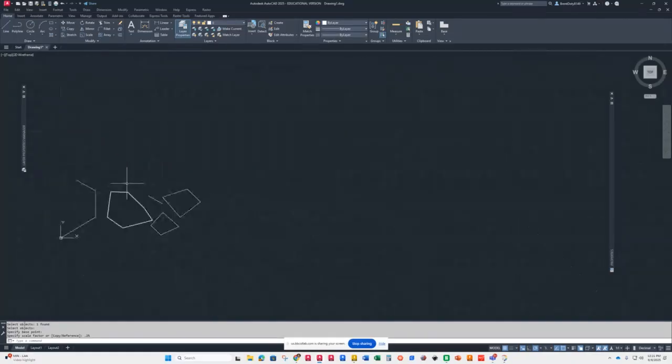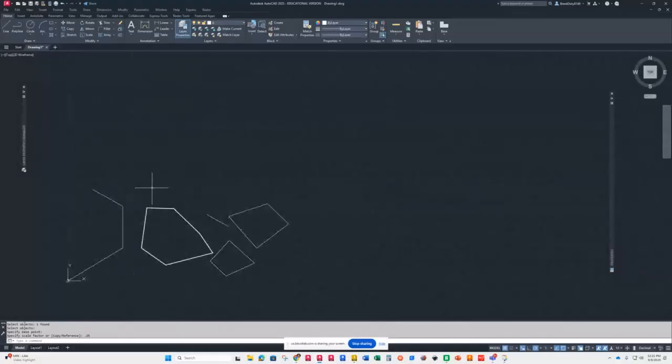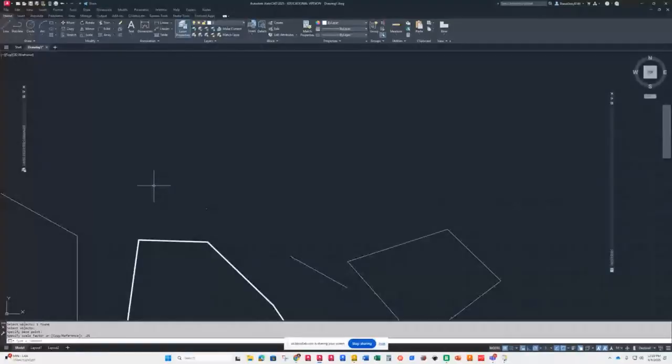All right, let's see, zoom back in and out. So to zoom in and out, all you do is push forward and back. Now, did I set my limits for this? No, I did not. Should I have? Probably, but I really am just randomly drawing things, so I don't really know how much area I need. So what the heck, why do I need to do limits? Well, eventually my zoom's not going to work. It might not let me draw outside my limits. So let's just look at what the heck are limits.